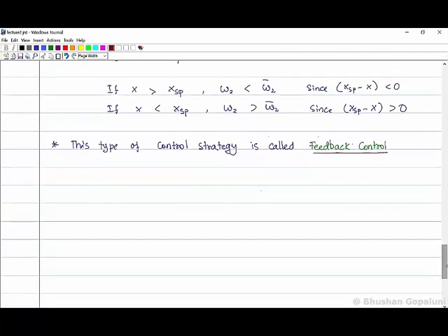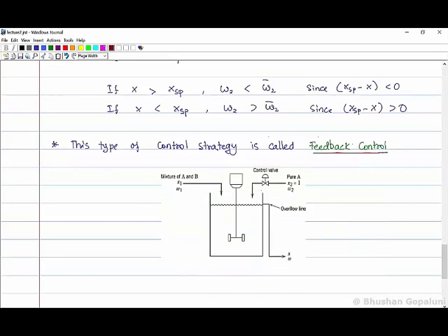So in order to implement a feedback control strategy, we need a few components, a few hardware components. For instance, to run the algorithm we have come up with in this context, we must be able to measure the concentration of X in the exit stream. Let's use a sensor. I'm denoting it here with AT. AT stands for analyzer transmitter.